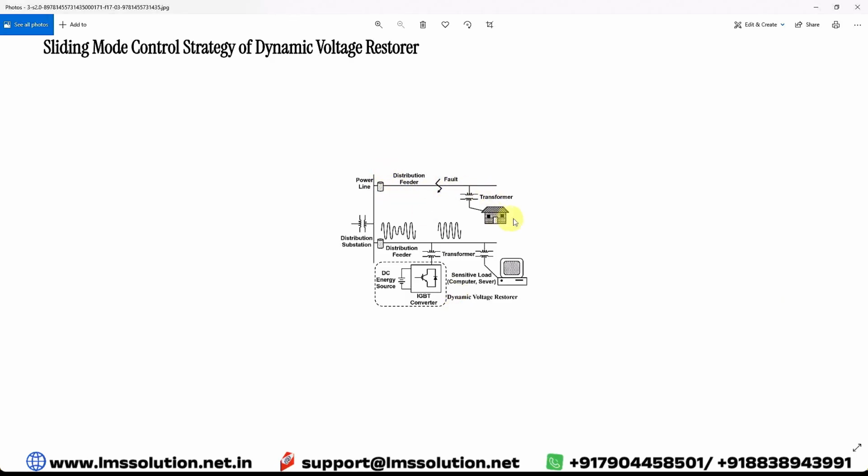One line is connected with the domestic load and another line is connected with the sensitive load, like a computer and server. For example, say a fault occurs in this line of the distribution feeder. Because of this fault, what will happen? A voltage sag will occur in the distribution feeder. When the voltage sag occurs, it is going to affect these sensitive loads.